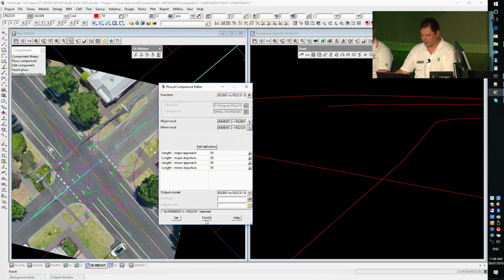All I'm going to do now is hit set, and all our strings here will adopt vertical geometry. And look, the vertical geometry will solve most times, but it's probably not something that you'd use all the time, okay? It gives you an answer, but it's very difficult to press a button and just generate vertical geometry that works.